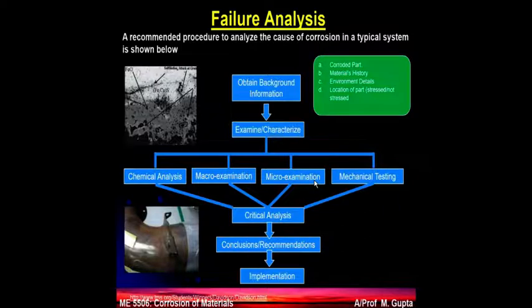Stainless steel is not good enough, 304. Then 304 is not good enough. You have to find out whether it's 304 or 304L. So every fine detail is important. Then you have to find the environment: inside, outside, contamination, no contamination, presence of industry, no presence of industry. So you have to see around it, what you see, what you can practically record.